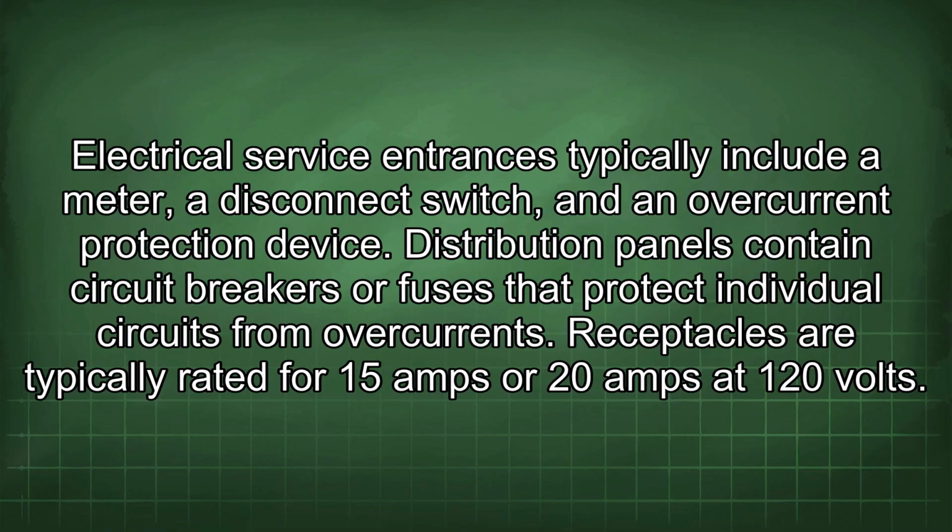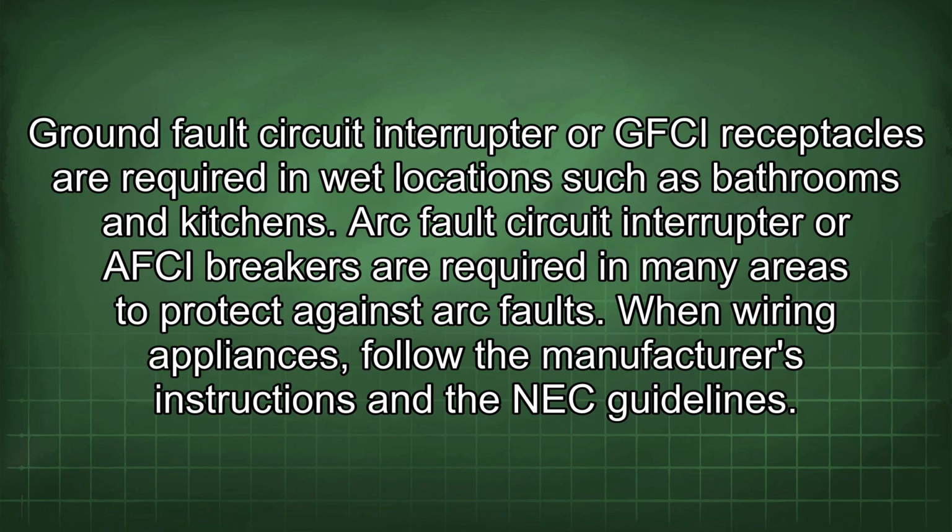Receptacles are typically rated for 15 amps or 20 amps at 120 volts. Ground fault circuit interrupter or GFCI receptacles are required in wet locations such as bathrooms and kitchens. Arc fault circuit interrupter or AFCI breakers are required in many areas to protect against arc faults.